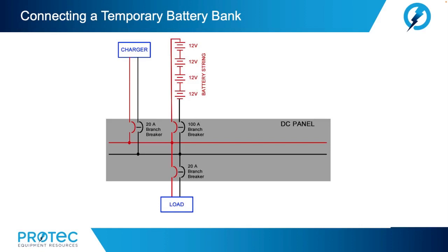If the battery charger is a filter eliminator type, it should be able to float the system while changing the batteries by itself. If it is not a filter eliminator, it should never be used to float the system without a battery attached. The non-filter eliminator chargers have an increased AC ripple that can damage the power supply on the DC powered equipment.